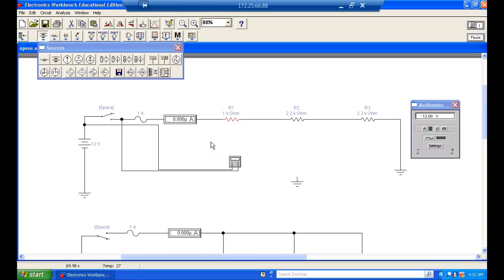We don't really say it drops voltage. It's just the entire voltage appears across the open, because nothing else in the circuit is dropping any voltage, right? You understand? So loads are acting like a straight piece of wire. That's what they act like. So even though right now, if I measured across this switch, it's going to measure 0. If I went over and turned it off, it's going to measure 120 volts.